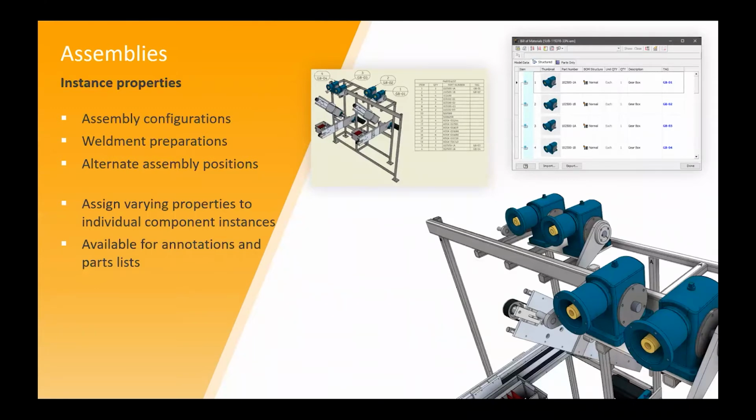If we open a legacy assembly containing levels of detail, you might remember the defaults: all components suppressed, all parts suppressed, and all content center suppressed. Those three have been removed, but effectively we have the master level of detail, and any user-defined levels of detail, including substitutes, are retained and converted to model states. They will be converted over in your new assemblies.